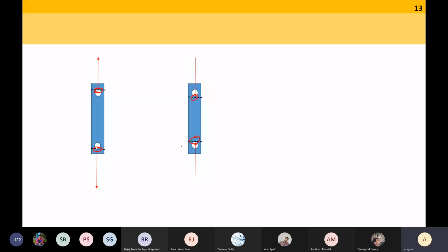The region above and below the points that I have drawn, the load is 0. So this region is stress free. This region is stress free. This region is stress free. Only this region is in a state of stress because the load has been transferred at this point. Beyond that point, there is no load in the member. So while calculating for tensile, I have to find out the critical region within these limits.